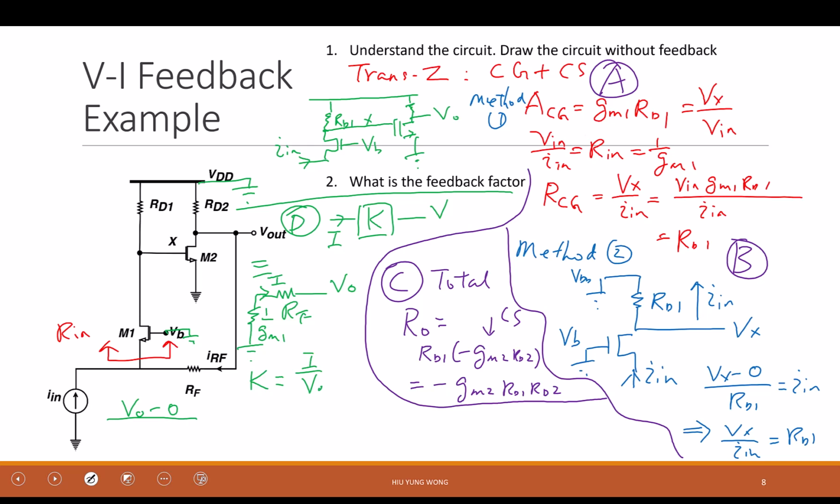You do negative. I keep asking this because we still take it for granted that we usually just say, I see this voltage divided by current is Ohm's law, but it's only correct in magnitude. Ohm's law is that you define the current from node 1 to node 2. If you define it that way, then the current equals voltage at node 1 minus voltage at node 2.